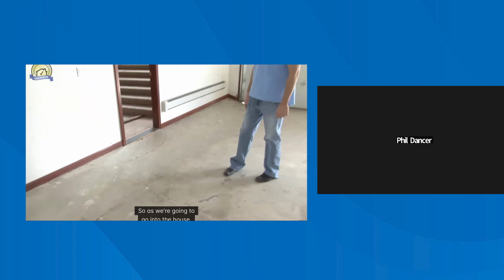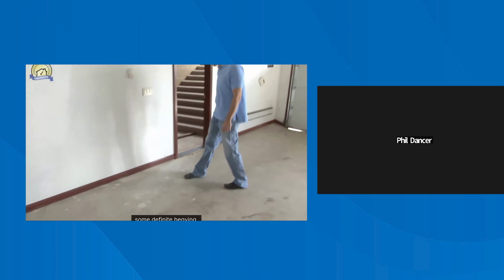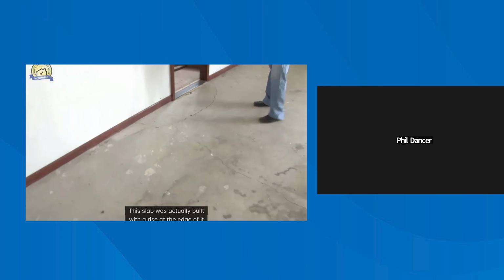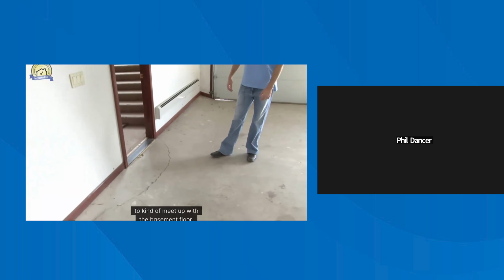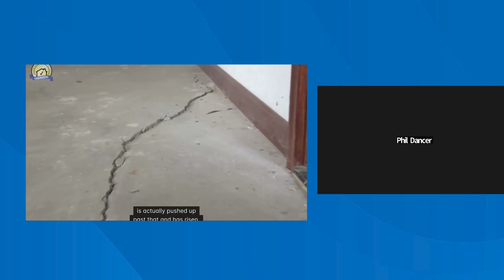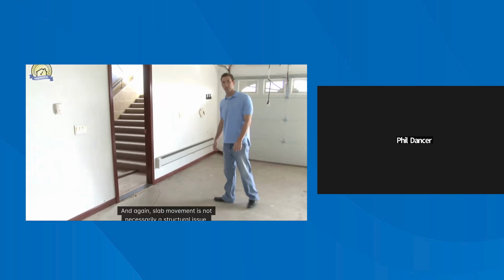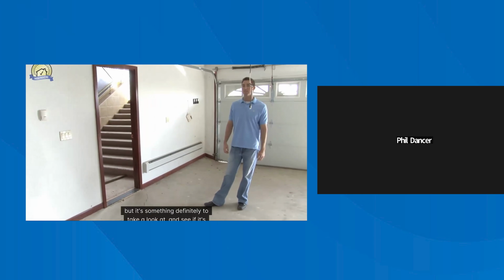So as we're going in the house, you see some more slab movement here. Obviously, some definite heaving. This slab was actually built with a rise at the edge of it to meet up with the basement floor. But you can see where the slab from the garage has pushed up past that and has risen. And again, slab movement's not necessarily a structural issue, but it's definitely something to take a look at and see if it's causing structural issues.